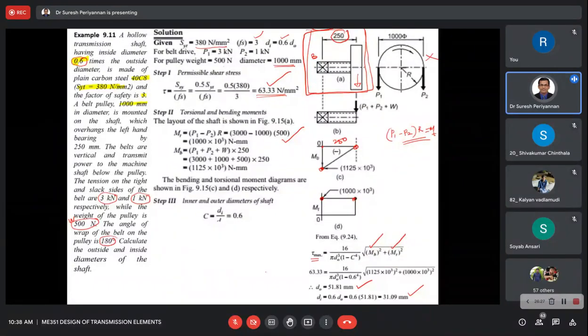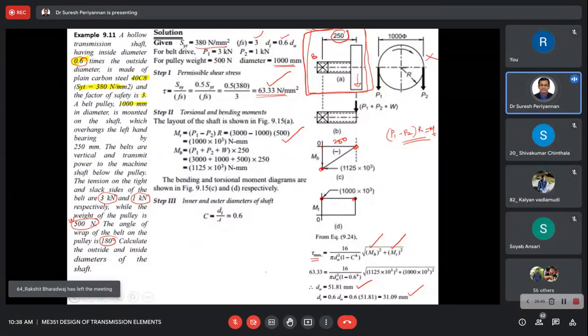So keys play a very important role. As I clearly told in the very first or second class, with just the shaft and pulleys we can't do power transmission. When we want to transmit power from one place to another, through a pulley or gear drive mechanism, the gear should be connected properly on the shaft.